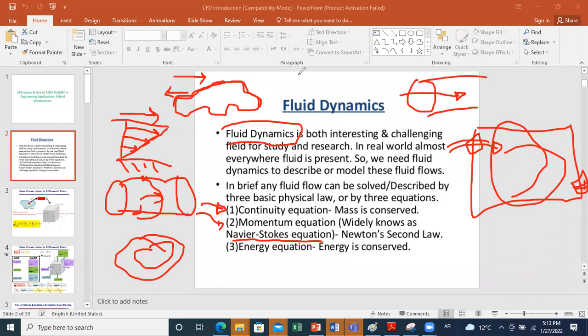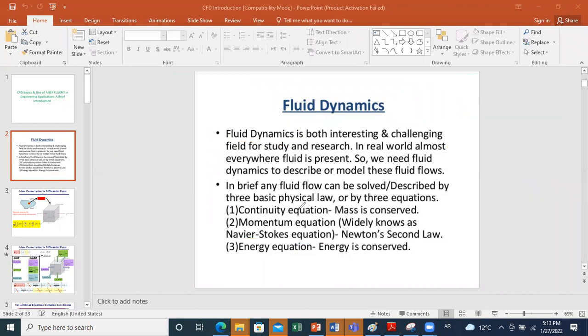Now, the second type of equations that is widely used, as we said, to obtain Navier-Stokes equation, is the momentum equation. And these equations consist of just writing Newton's law on your element. So sum of forces equals ma. And from here, we derive Navier-Stokes relations. I will remind you of the method to derive these in coming slides.